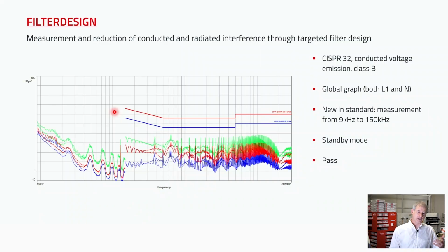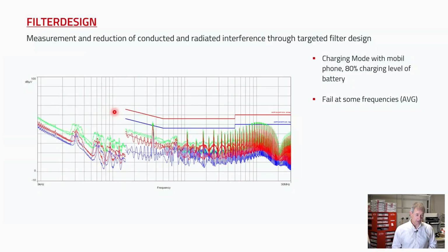Then we will change to a loaded system. I will put a more or less empty mobile phone on top of the Qi2 transmitter, and we'll measure the conducted emissions again. And what happens? We see the noise floor comes up a little bit. We have here also a peak at 360 kilohertz, which is what the new system is running on, like Christian said.